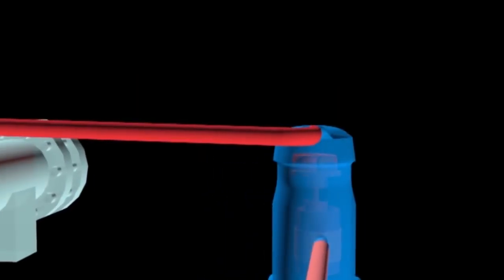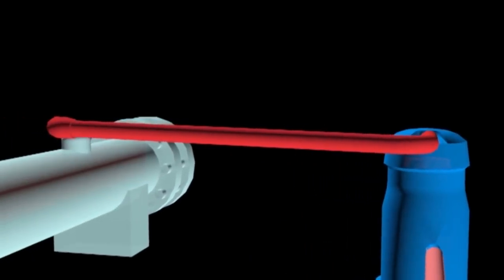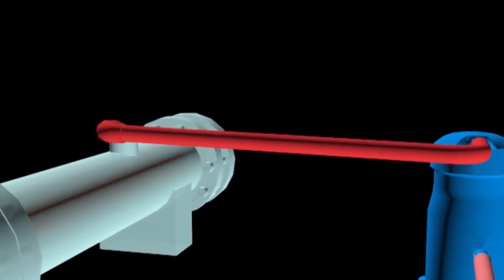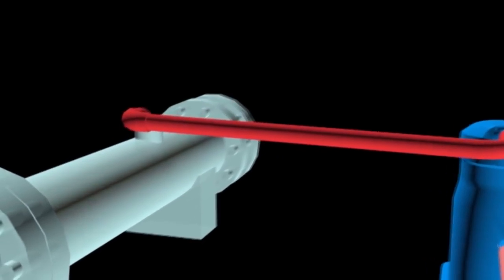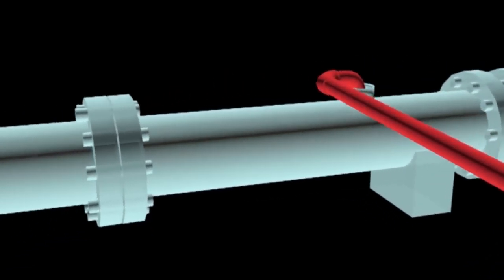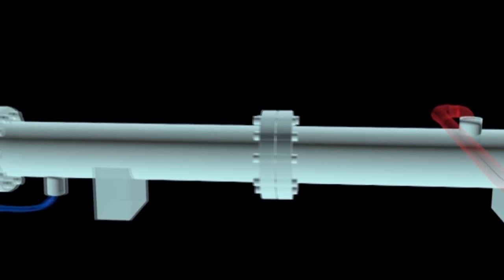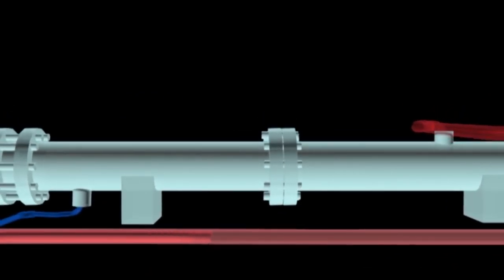Condenser. The refrigerant in high-pressure gas enters the condenser at a temperature higher than the temperature of condenser water. In the condenser, the heat will be eliminated to the condenser water from the cooling tower through the process of convection and conduction. After the heat is removed, the refrigerant in high-pressure gas is condensed into a high-pressure liquid